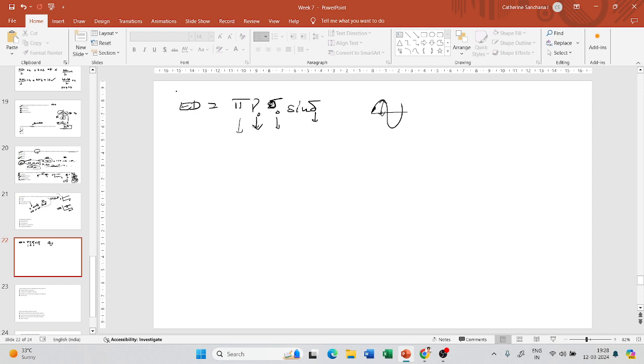So from this equation only we have got the two parameters, G star by sine delta and G star into sine delta. Now in these equations you do not have the term G star, right? You know that G star is the amplitude of stress divided by the amplitude of strain. So now we are simply going to replace stress and strain.